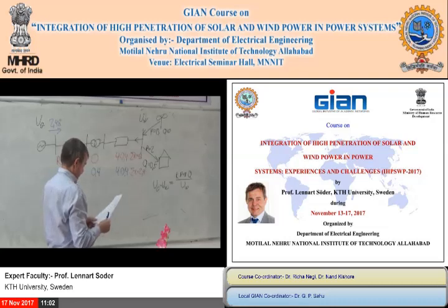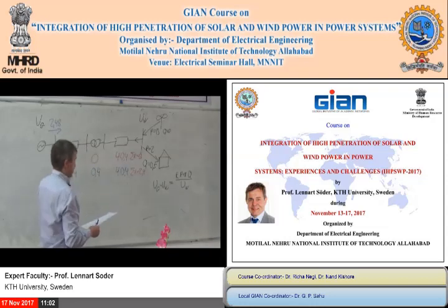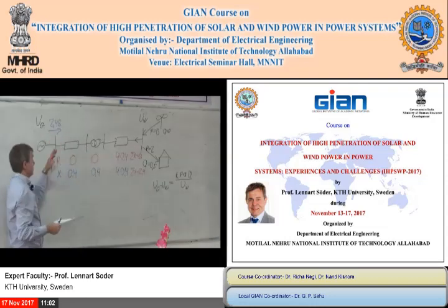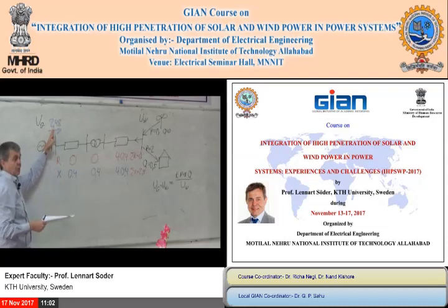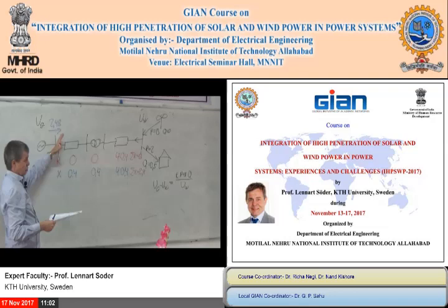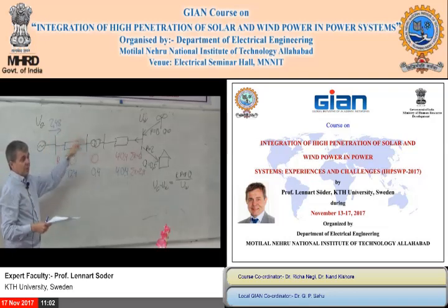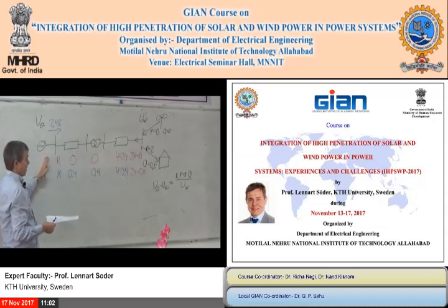So that was B. C: is it possible to use reactive power to both keep the voltage and, because this is an issue that is discussed nowadays, that this has to be supplied from somewhere. And the question is, because that is also what I discussed, that in the future system, when you have more solar and wind power out in the distribution grid, you want still to keep the voltage here. And here you suddenly start to consume a lot of reactive power.